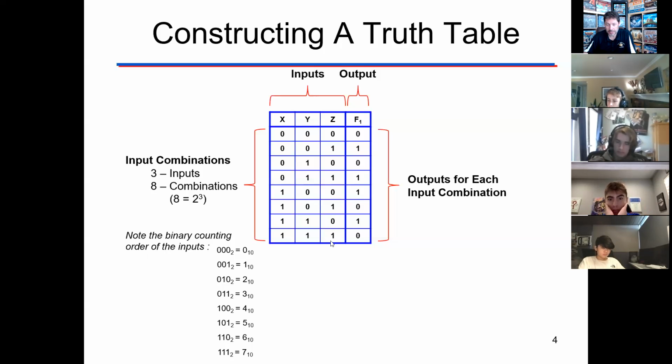And you may notice that when Z is on, there's multiple times when you get an output that's 1, but then there are 2 times when you get an output that's off. So we have to consider all the combinations. There's maybe multiple sensors and we're looking for specific combinations to give us an output that's on. So there's only 1, 2, 3, 4 combinations of inputs that actually tell the output of the circuit, you need to turn on the siren or you need to turn on the light or whatever happens to be the buzzer. There's only 4 combinations that would create that positive output.